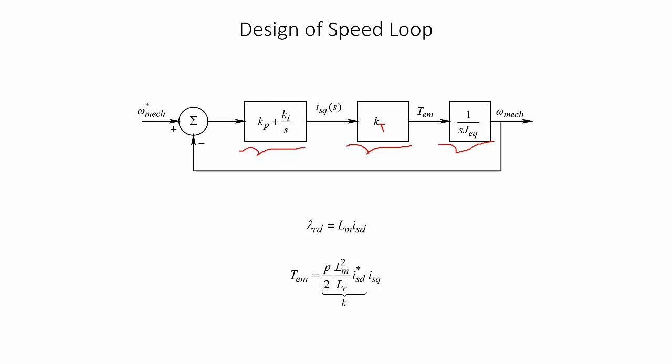And that is given by this formula, which we had seen in the previous slide, which was obtained by the simplifying assumption that in vector control, we are going to align our DQ frame with respect to the rotor flux linkage space vector. And this whole thing can be assumed to be a constant because ISD is maintained a constant, or in the cases where ISD varies due to field weakening, it varies at a rate much, much slower than the speed at which the electromagnetic torque changes.